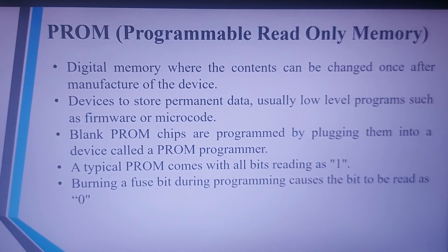So burning a fuse is nothing but writing a program into it. We know that once the fuse is burnt, we cannot fuse it back. Once it is burnt, it is over. It cannot be made an original fuse again. That's why these are all one-time programmables.